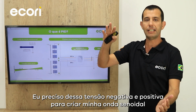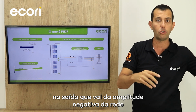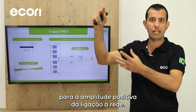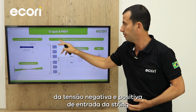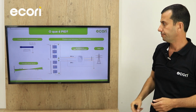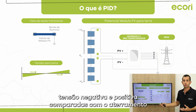And I need this negative and positive voltage in order to create the sine wave at the output, which is going from the minus amplitude of the grid to the plus amplitude of the grid connection. So I have this minus and plus, and I need to create them from the minus and plus voltages of the input string. So we understood why we have negative and positive voltage compared to ground.